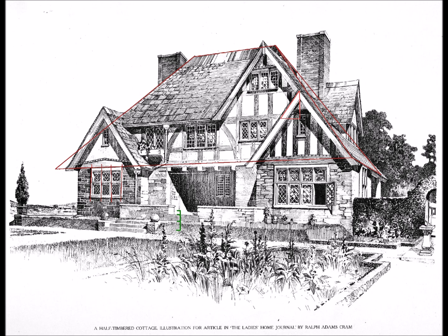Nowadays, houses typically have fairly low roof slopes, like 4 inches of rise for a 12-inch run, or 6 or 8. Anyway, we're going to go with 14. I played with it a little bit in the model, and that seems to be pretty close to what's there. It was also a figure commonly used at that time, 14 and 15. I looked at 15 as well, and 15 was a bit too steep compared to this picture. So that's what we're going to use, 14 in 12 for the roof slope. Now we're going to shift over to the model itself, and I'll show you the bare bones, the basics at this point.